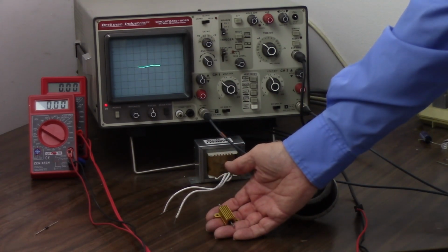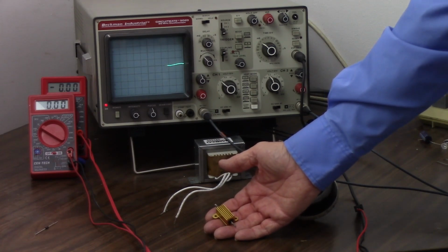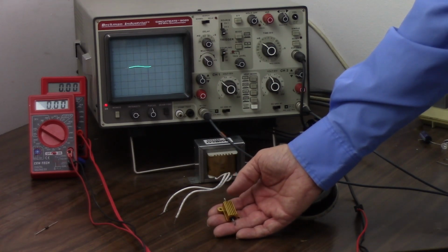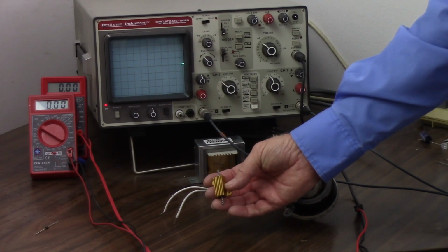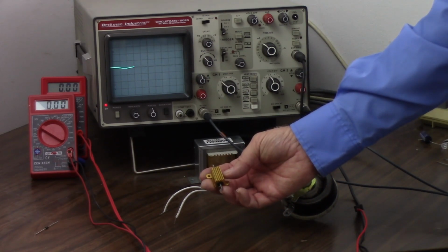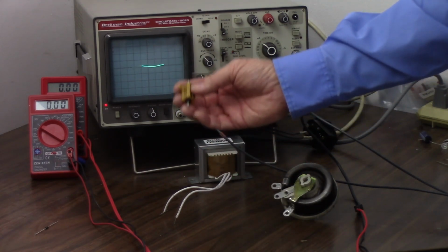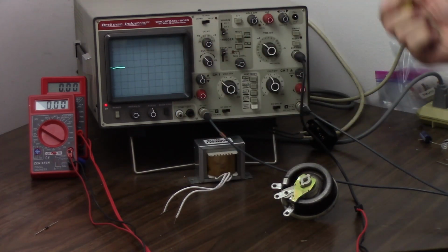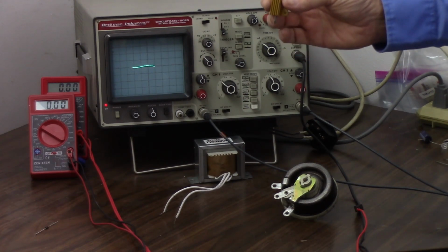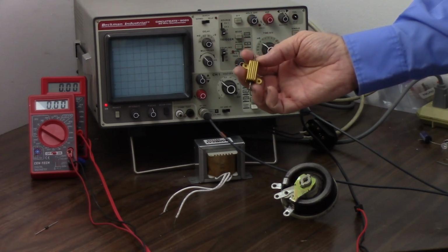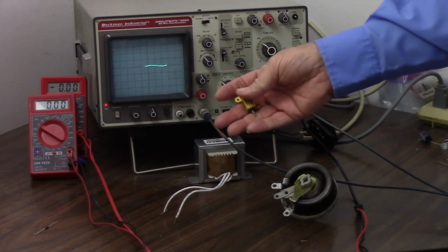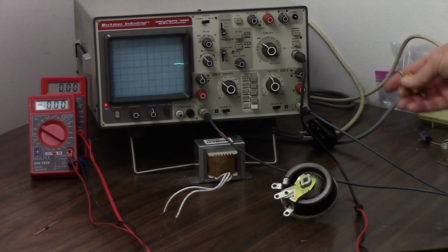But my AC voltmeter really doesn't have the resolution. I would be at a 200 volt range, and I'd only be looking at the last digit to look at 100 milliamps, 1 volt per 100 milliamps, and I don't think I'm going to be able to trust the accuracy of that method. So I could use an even bigger resistor, but then I would be affecting the whole circuit by adding more resistance. So I don't want to use that method.